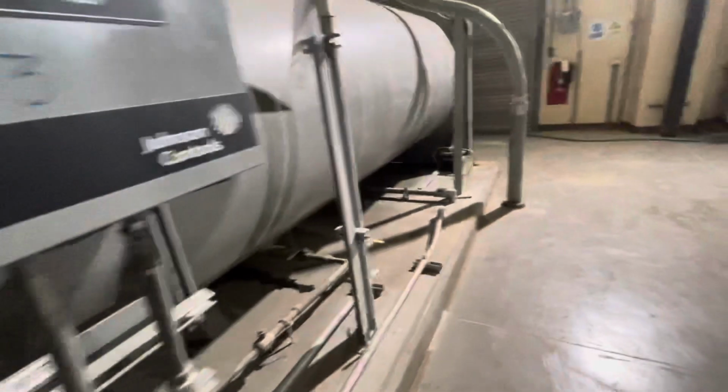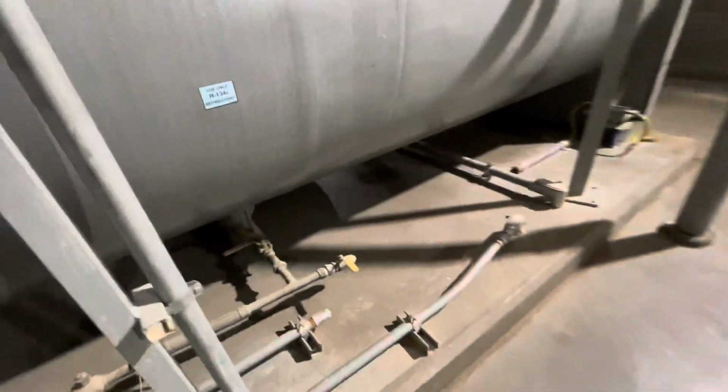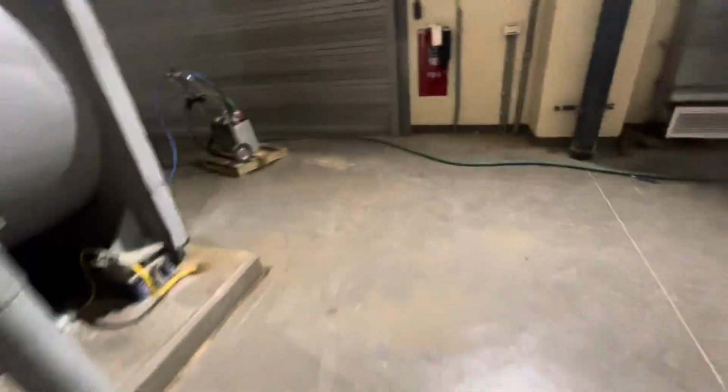And this is the side glass where you can see the level of the refrigerant. If the refrigerant is less, it will not show here. Or if the LCV is not working, it will not show. This is the RLDS sensor. If there is any leakage, more leakage of freon, it will sense and give an alarm that there is leakage of freon. Now our tube cleaning is continued. You can see here.